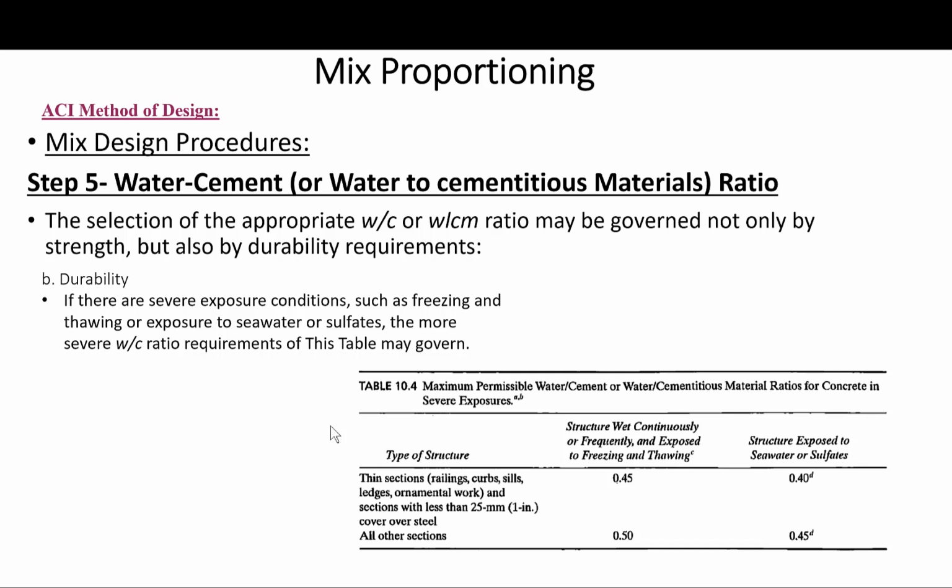Okay, so we talked about the implication on strength. Let's talk about durability. If there are severe exposure conditions, such as freezing and thawing, and exposure to seawater or sulfates, the more severe water cement ratio requirements of this table here, 10.4, may govern the selection of the water cement ratio.